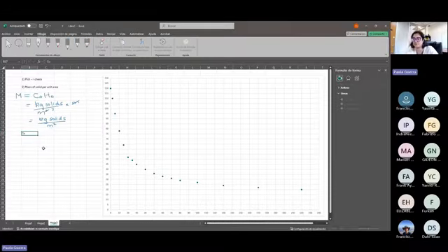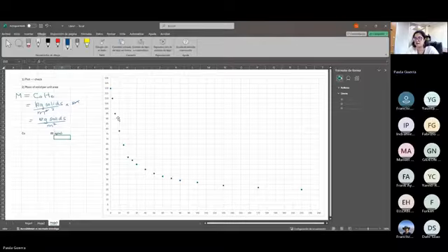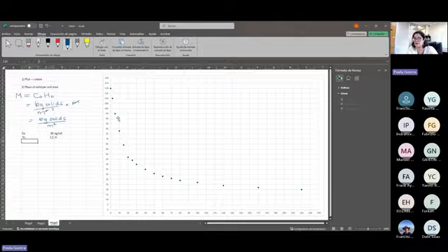So if we calculate this using the data that we have, remember that C0 was 80 kilograms per cubic meter, and the initial height is 1.2 meters. So our M is 80 times 1.2, and that would be 96 kilograms per square meter. So we have the first thing now calculated. Let's move on to the third point.